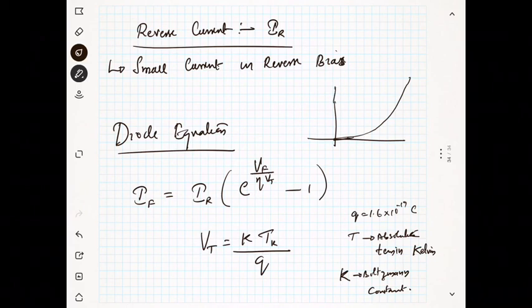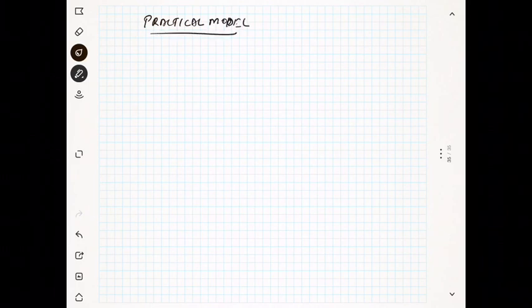Okay, this is the actual diode current. So we will see some more details regarding our ideal, practical and complete models. First, the practical model, in forward bias and reverse bias. In forward bias, I told you in the practical model it's 0.7 and a short circuit.